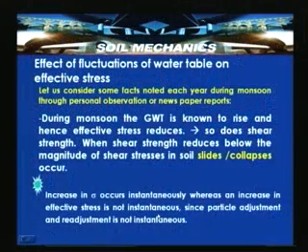One thing we should note is that an increase in total stress sigma occurs instantaneously, whereas an increase in effective stress is not instantaneous, since particle adjustment and readjustment is not instantaneous.